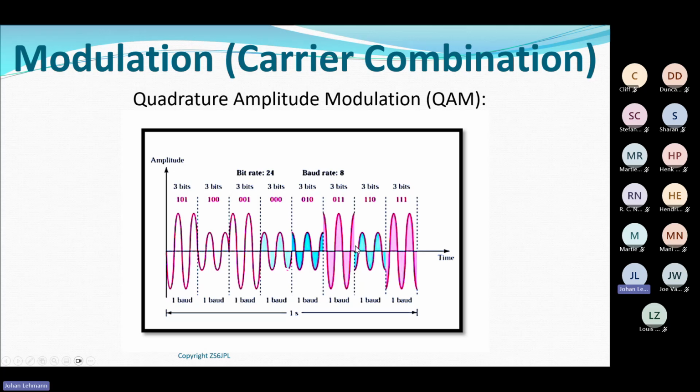So they've expanded this and made it bigger and bigger, so you get even more complex QAM methods. But for your exam, this is the only one which is important: every time there's a state change, I change either the amplitude, or I change the phase, or both. And that is quadrature amplitude modulation. Hope it sank in. I'll leave the graph there for a second to view. If you just want to study it and see if you see the pattern of the data versus the change in modulation.